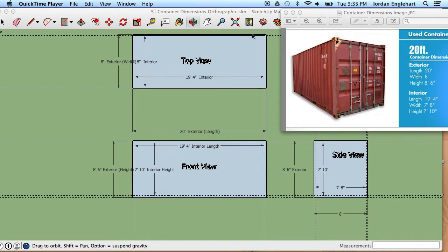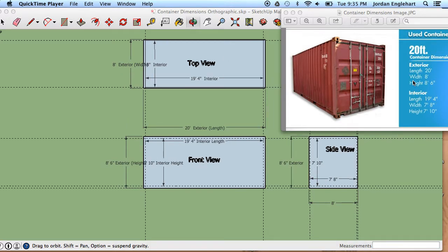I know you know how to do it from class on paper, but we will actually take this top view that we make here and you'll use that when we lay out our plans for how to actually build this thing. So once again, we have our length, width, and height. Our orthographic view gives us that. We have our length and our width by seeing the top view. Front view gives us our length and our height, so we know how tall it is. And then the side view, which would be these doors over here, we can see the height and the width.